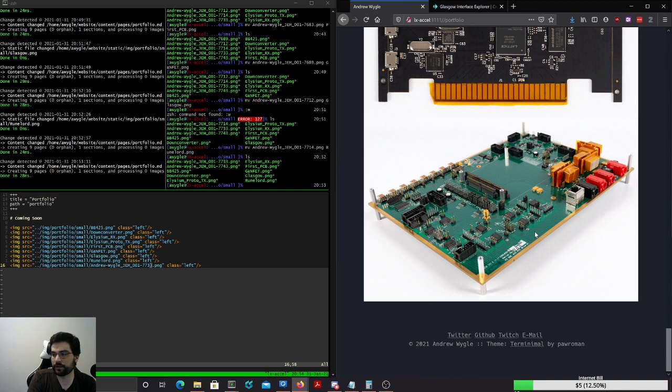This project sucked to work on. It's not the technical side so much as that everyone had different requirements that basically couldn't be unified, and then I delivered a product that nobody was happy with at the end of the day. Also, this is where I learned about MOSFET body diodes, because these are supposed to be solid-state relays, but when you have body diodes, that doesn't work, and they all leak into each other. So we replaced them with tiny boards built of physical relays, which obviously don't have body diodes.